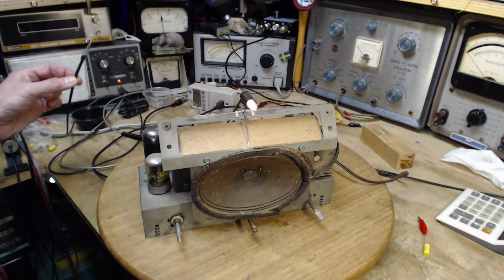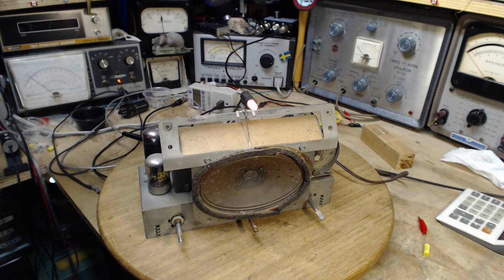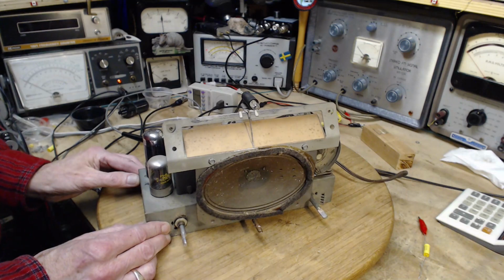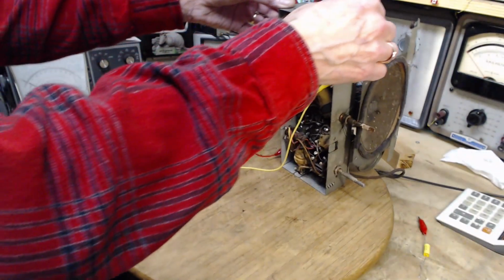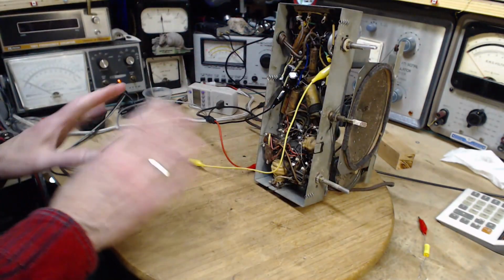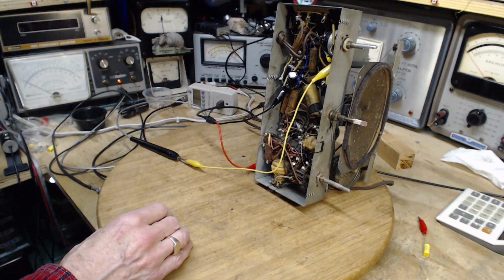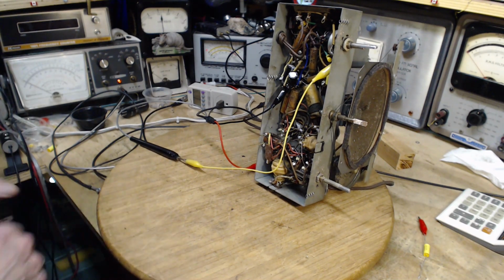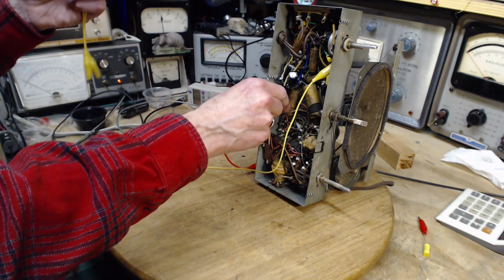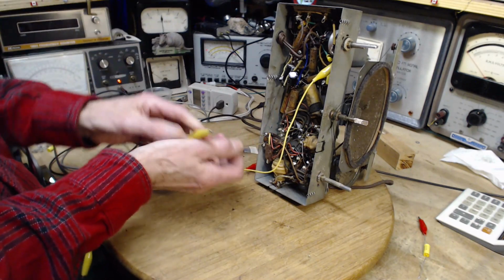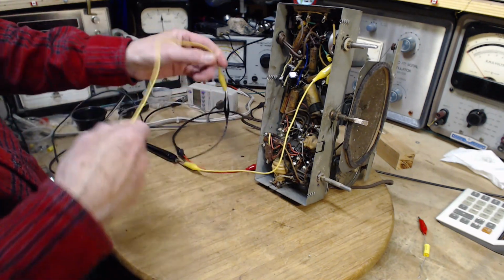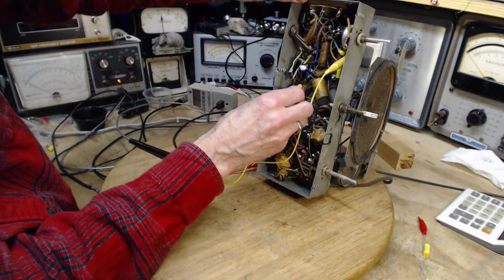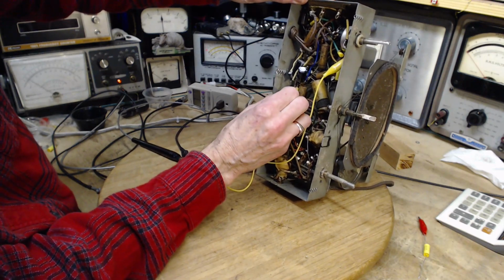Okay, so I'm thinking I've got to connect this. I have to go up here. So I don't want to put two grounds in two different places on the radio, like the chassis and the B minus. They got to be together on this. Okay, I don't think I want that big clip lead in there. So what I'm going to do, I'm going to separate this here. Connect this to the B minus.